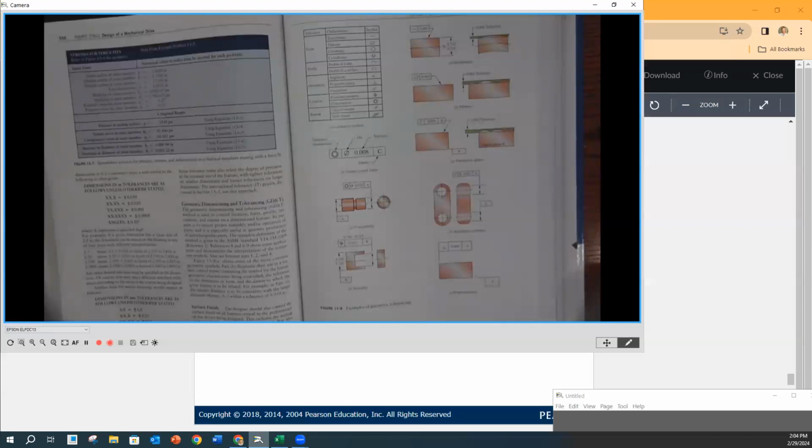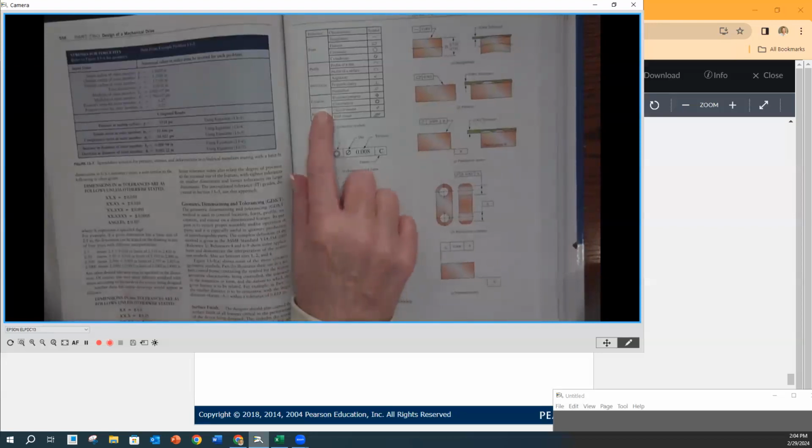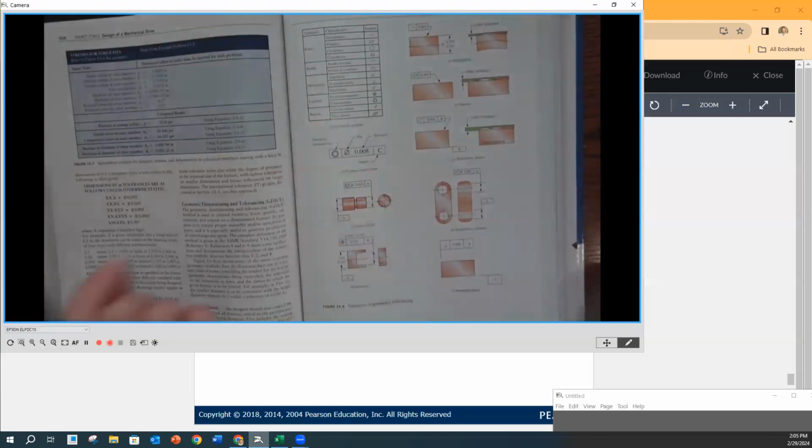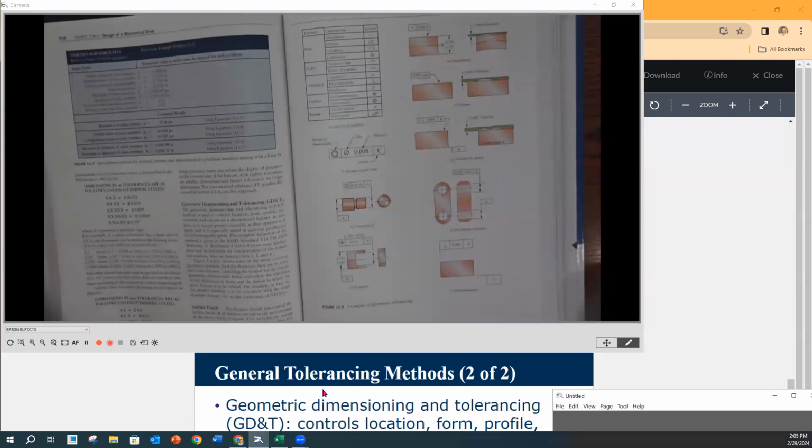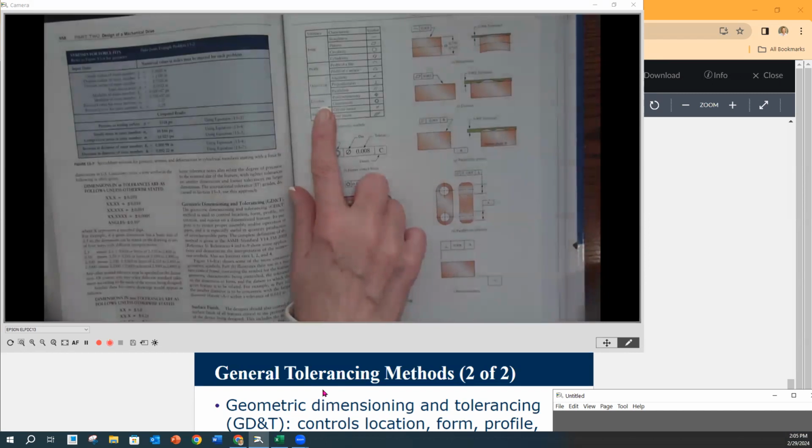acceptable tolerance. Now, I didn't teach you guys GD&T, and I'm certain Phil was very thorough in that. Did he also mention location? When you use position tolerance, it really should be used on all locations. And you don't see it all the time. Companies that know GD&T will, but companies that don't, unfortunately, will just try to control position with rectangular coordinate dimensioning. And you get more acceptable tolerance area when you use position.